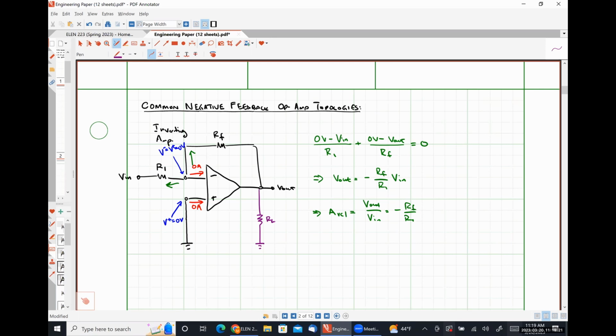Another place I can put a resistor to mess with you. I'm just going to call this resistor here R plus. It's connected to the non-inverting input node. Will it have any effect whatsoever on our relationships? Absolutely not. Very regularly when we make op-amp circuits, though, we'll put some resistance there.